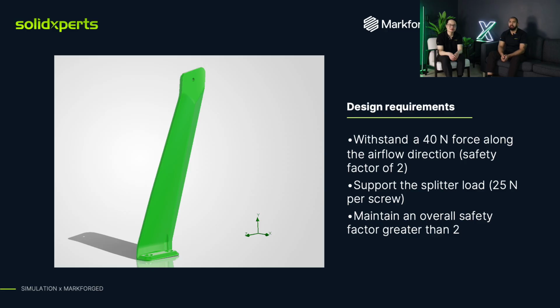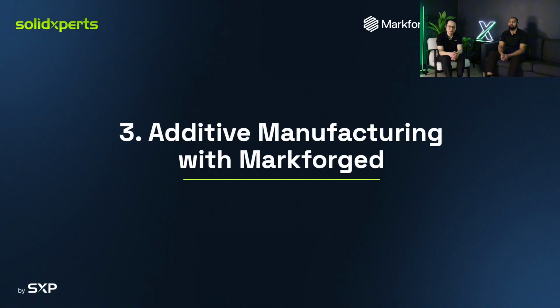So from there, we're going to select a manufacturing method. Here, we chose additive manufacturing, specifically with our Markforged printers. The reason we chose this method is because it allowed us to have prototypes to use on the cars as quickly as possible, and with a relatively low cost per part for a small quantity of parts, considering we only have 3 cars that actually needed these reinforcements.